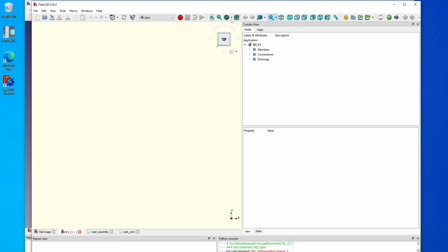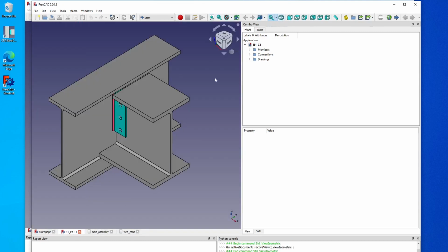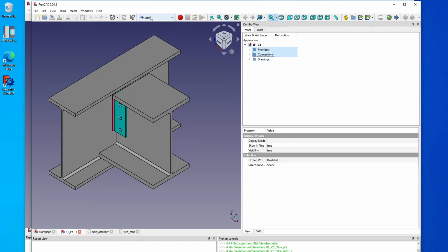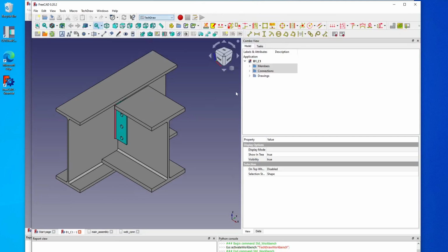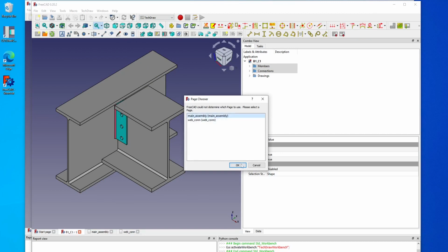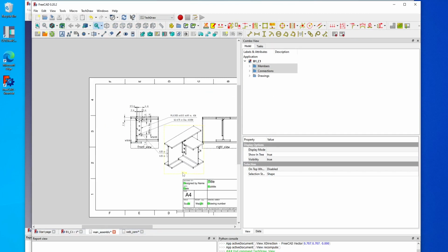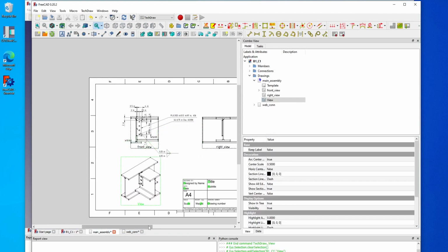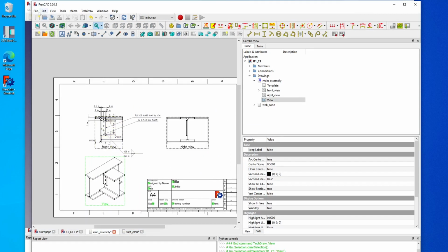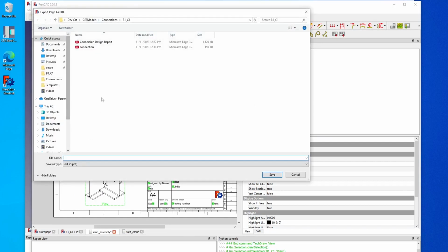Now, select the 3D drawing model and access the TechDraw workbench. From there, you can incorporate an ISO view into your drawing. Additionally, users have the flexibility to customize drawings by adjusting dimensions and then exporting them to PDF for future reference.